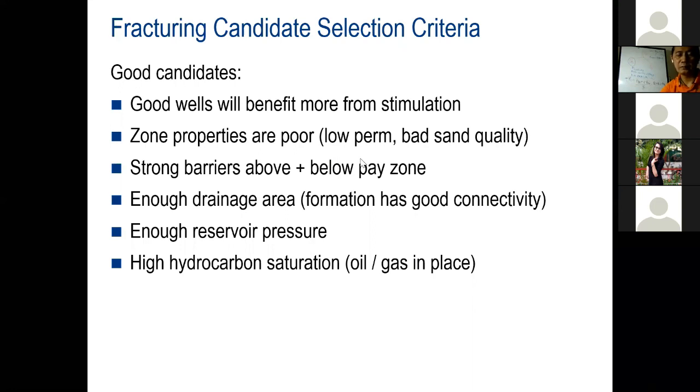In the US, for example, if you want to drill a shale gas reservoir, you don't have any option but to frack it, because if you want it to flow naturally, it's impossible. Super extra low permeability, you have to frack it. That is why all the shale gas and shale oil development in the US and other parts of the world use horizontal well completions and then multi-stage fracs, right? One horizontal well maybe 3,000 feet, and they put like 10 or 20 stages on it.